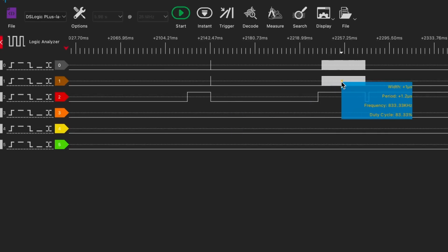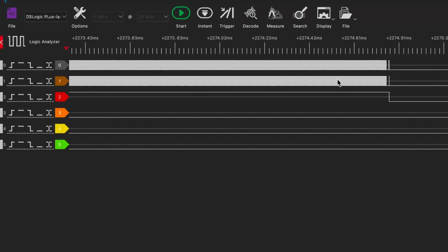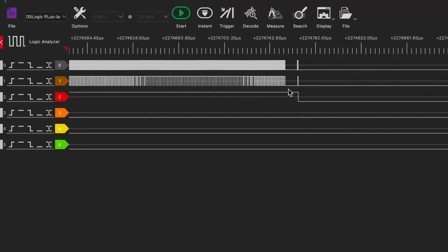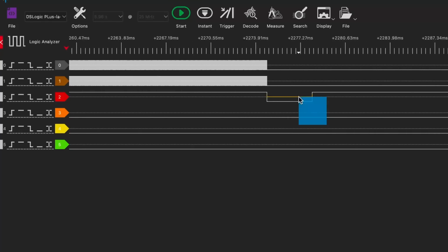In fact, this is a capture from not exactly the program I showed you before. I write more stuff to it, but it doesn't really change anything. But take a look at the end here. I sent a 0x12, asking it to start a refresh. It does seem to refresh. The issue is the refresh is only taking 3.4 milliseconds-ish. This is definitely not correct.